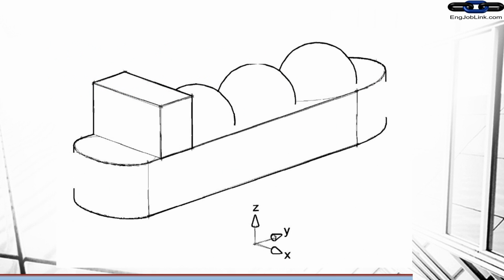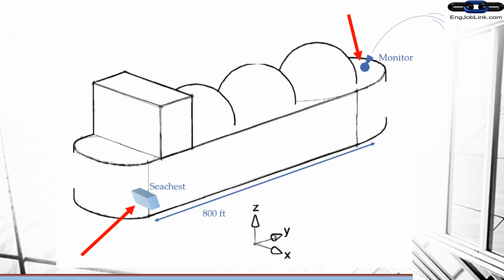Our important parts are going to be the sea chest, where we'll draw seawater from. And we want to send that seawater to a monitor all the way at the front of the vessel on the pointy end. And then we need to know a distance in between, and height of installation, deck height, and then the vessel breadth is helpful, just for routing purposes, or general routing.